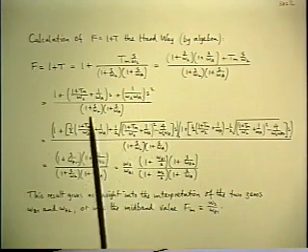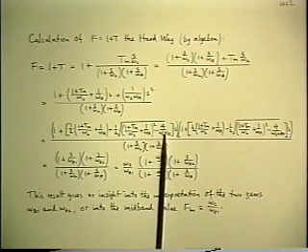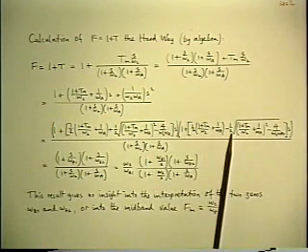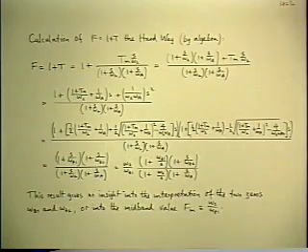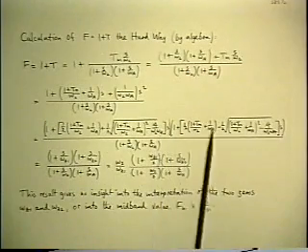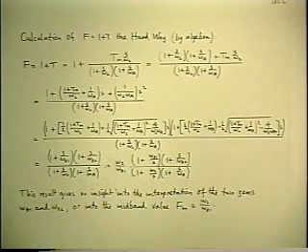And then if you resort to the conventional formula for the solution of the quadratic, this is what you have to substitute for the two roots in order to write the two factors of the numerator to find the two zeros. And you see what a ghastly mess that is. You have this whole long expression in the square bracket representing the new corner frequency that we found so easily.